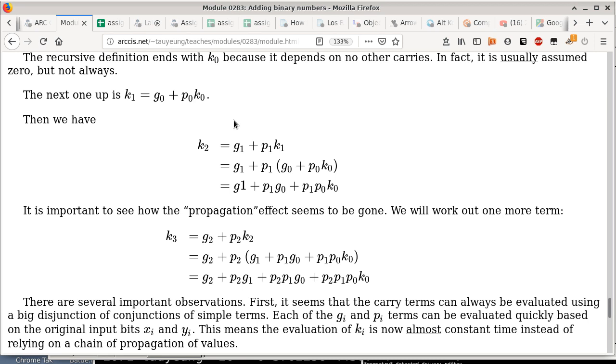So that means the result of this, well, this one is a little bit extra because it doesn't have an AND gate, but I can get to the result of these at the same time. This is already done by the time the other 2 are done. So now I just need to take the result of this, the result of this, and the result of that, and feed them into an OR gate, and I have the final answer. Is that okay?